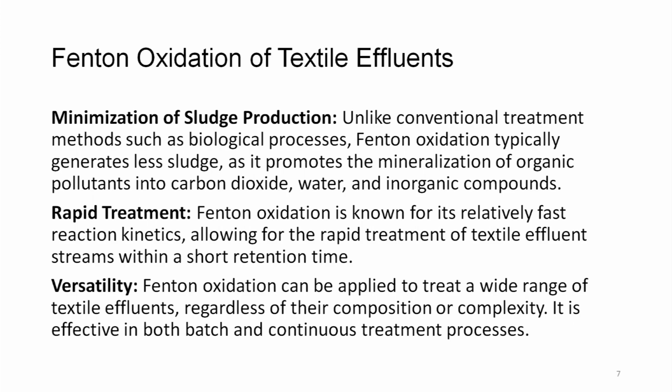Fenton oxidation can be applied to treat a wide range of textile effluent regardless of their composition or complexity. It is effective in both batch and continuous processes. So, Fenton oxidation is not only fast, but it works on both batch and continuous processes.